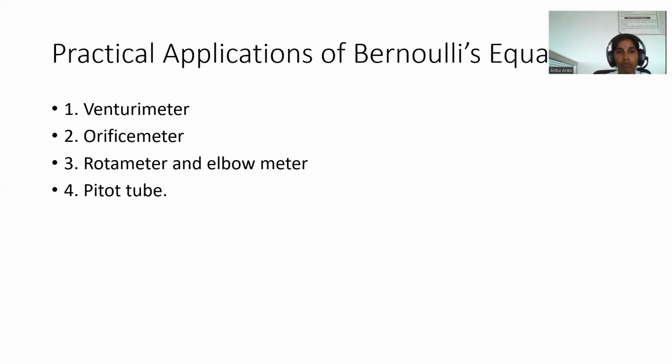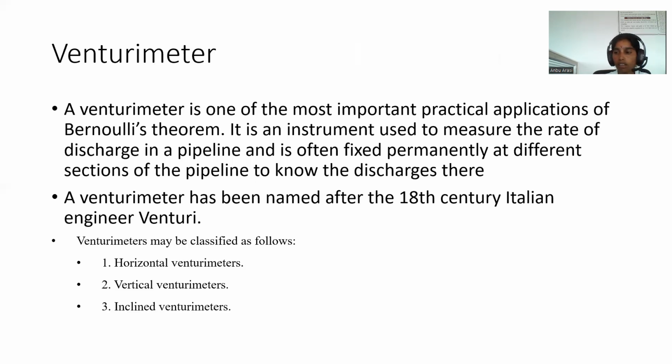Practical applications of Bernoulli's equation. Bernoulli's equation is applied in all problems of incompressible fluid flow where energy considerations are involved. But we should consider its application to the following measuring devices: venturimeter, orifice meter, rotameter, elbow meter and pitot tube. Venturimeter.